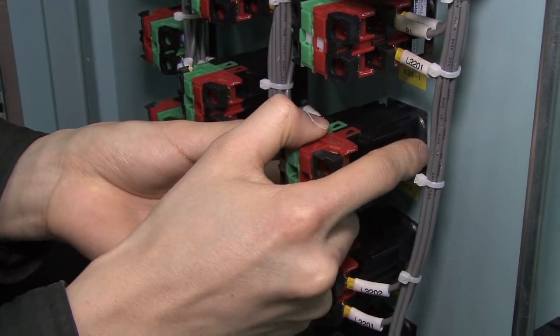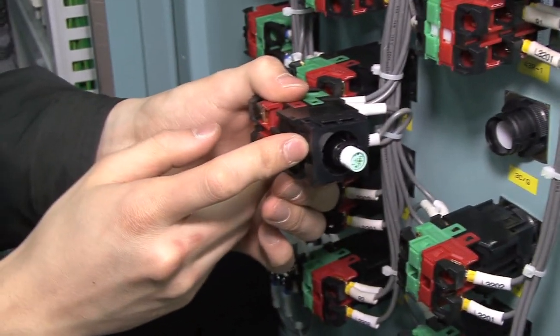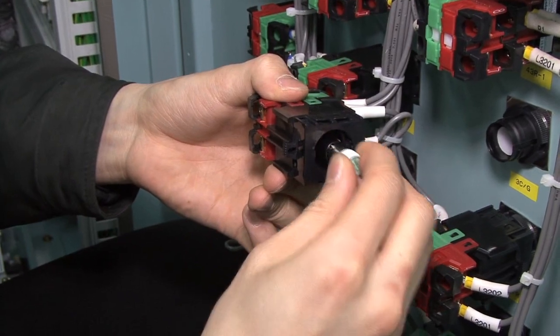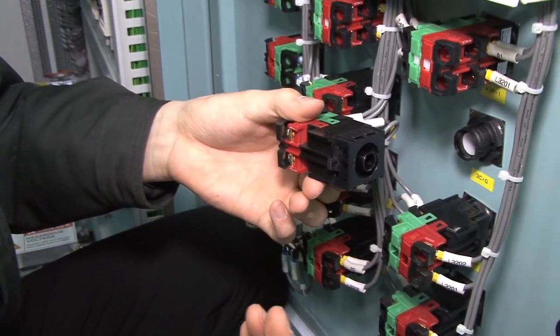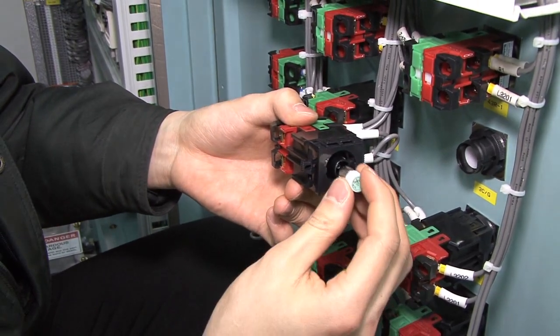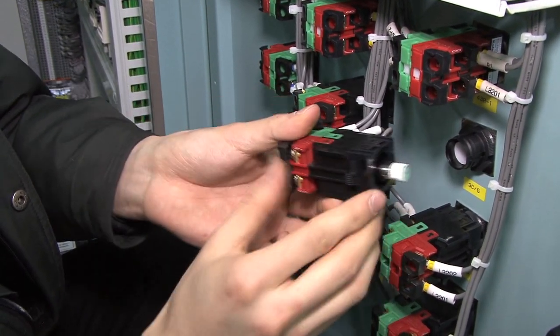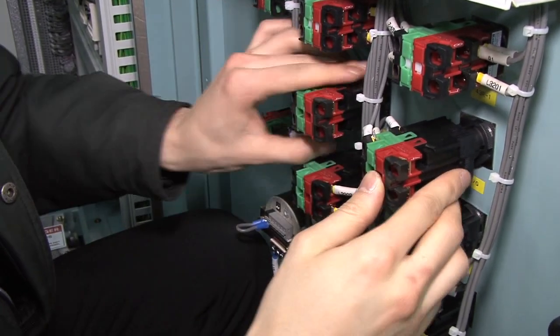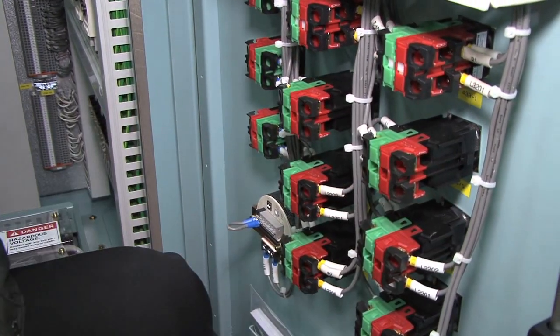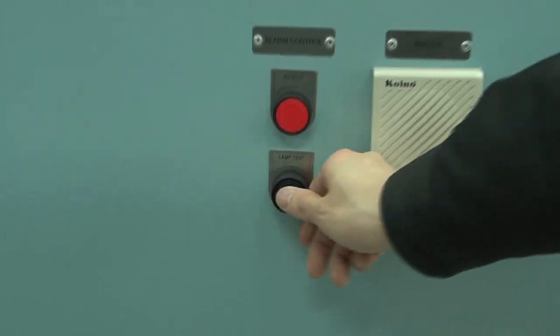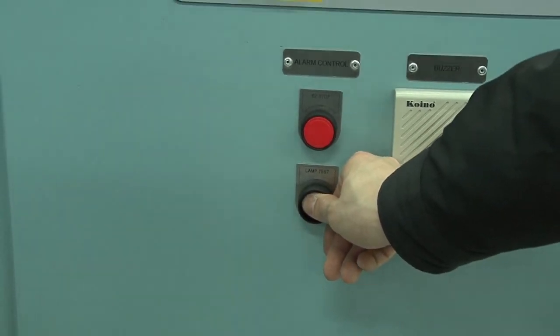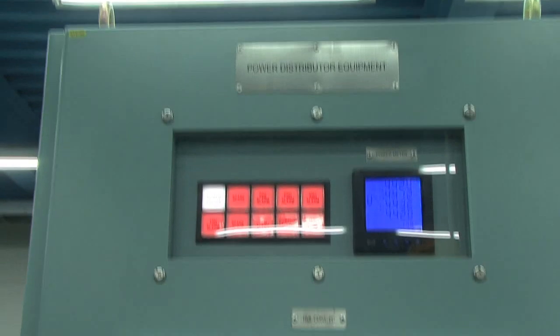Lamp bulb. Applicable equipment and location, PDE. Step 1. Take apart the power part of button lamp and remove the defective lamp by turning to the left. Step 2. Remove that defective lamp by turning 90 degrees to the left while pressing inward. Step 3. Check color and voltages of a new lamp and replace it, following instructions in reverse order from Step 2 to Step 1. Step 4. After the power is on, check operation of lamp. Lamp light.